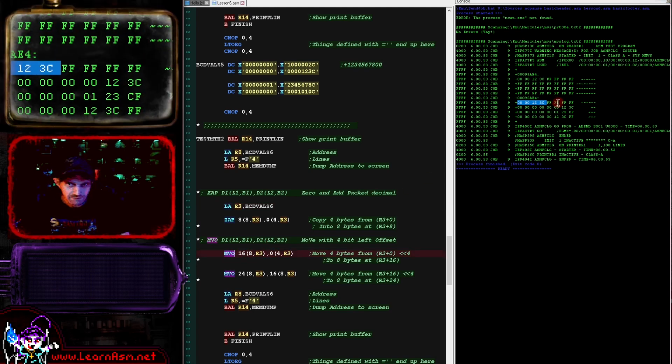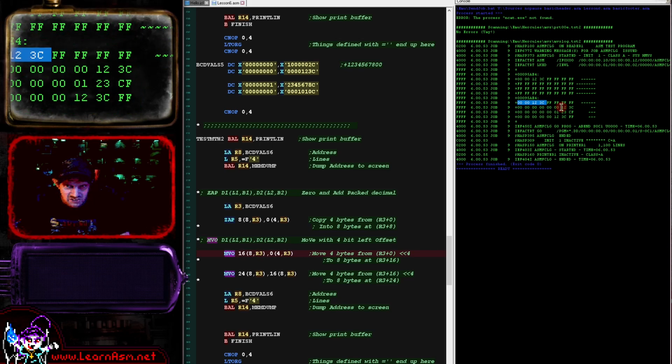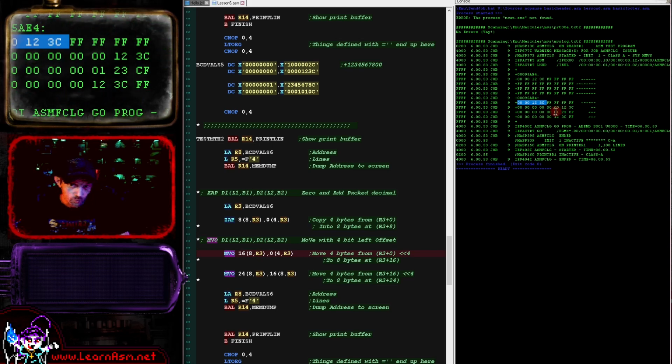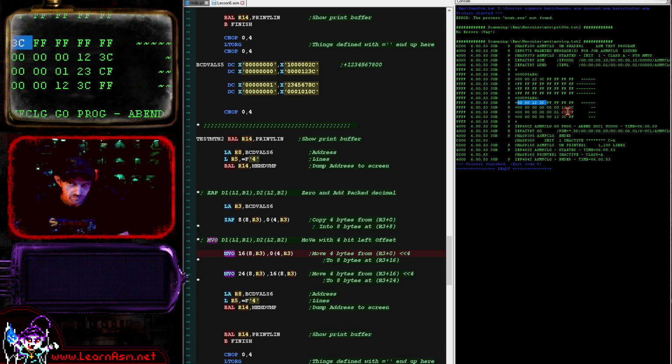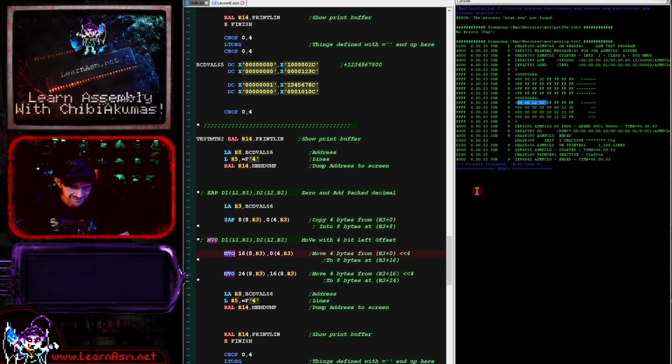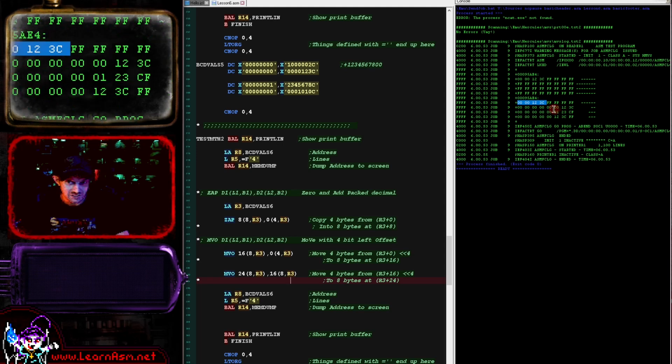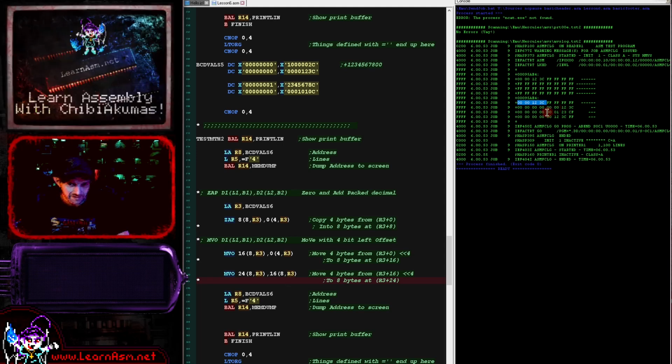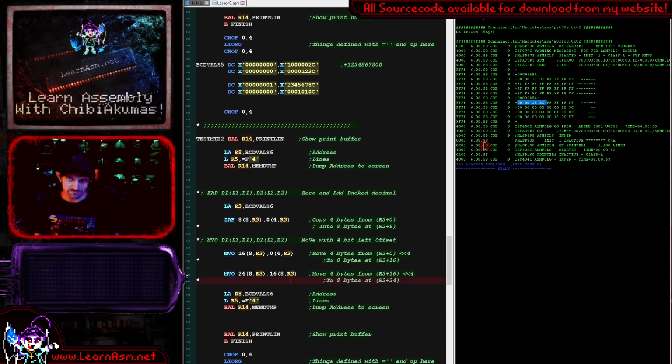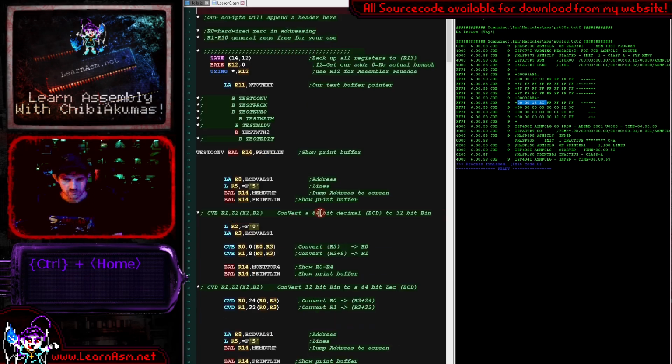So you can see that every time we run this, we're effectively shifting by 1 digit to the left, 4 bits to the left each time. Now, as I say, it's not quite a rotate command, but that is what it is intended as. So we're shifting by 1 digit. Of course, if we needed to shift by 2 digits, we could literally do a regular copy there. But this shifts by a single digit, so allows for a half-byte offset effectively. So there we go. So that's what that does.